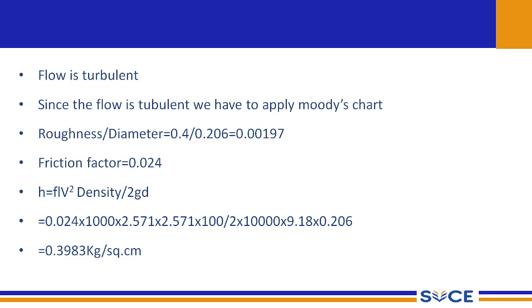so that it satisfies the pressure and the temperature rating. So this is a small calculation which indicates how to perform the line sizing for an incompressible flow when you have water that is getting discharged in the velocity range of 1 to 3 meter per second.